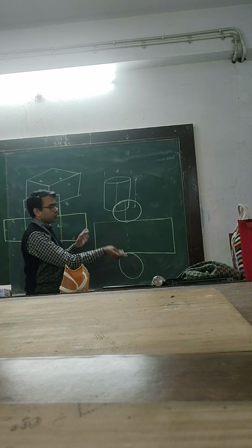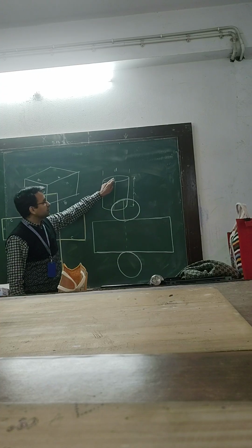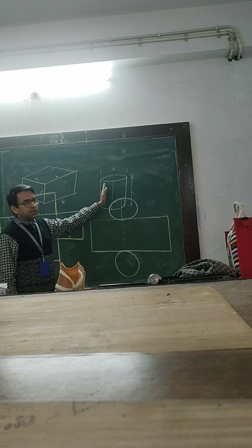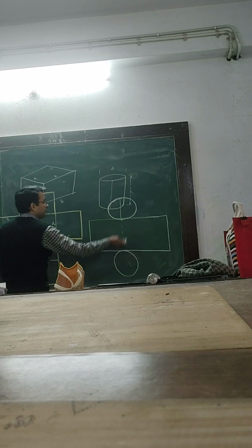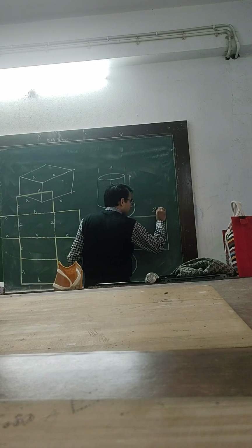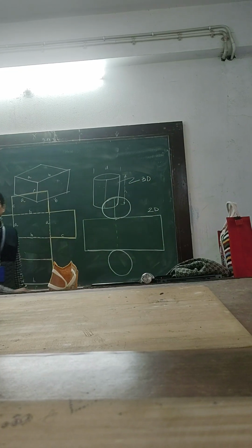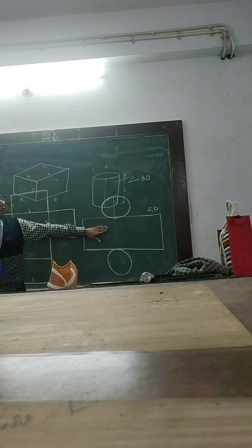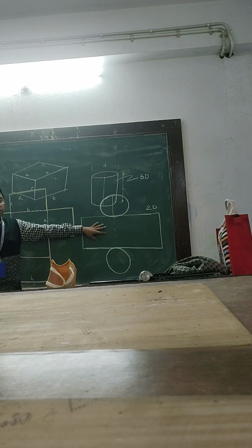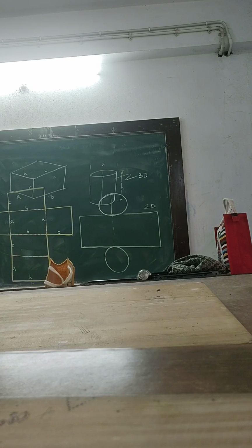Now basically you roll it and make the shape of this cylindrical surface. Curved surface complete. The lower one is the plane surface and the side is the curved surface. So you will produce this from this, because this is 2D and this is 3D. Right? So this is called the development of surface. That means you want to produce this, so this is developed first, then you produce this. Right? So this way you can do all the surface development.